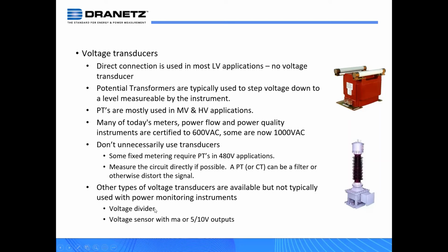A voltage divider has a better bandwidth, as Ross talked about earlier, because the idea is not to attenuate any PQ events that are causing the problems. You want those events to reach the instrumentation and not be attenuated by any in-between devices. So we find that a voltage divider has a better frequency response to allow those transients through.